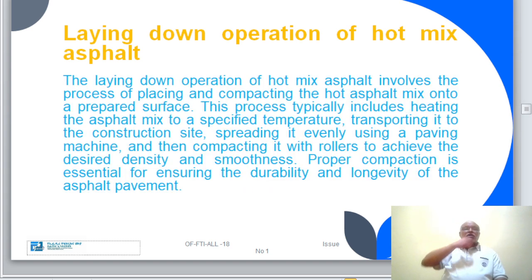The track paver, owing to its long and stable track, assures very good grip, stability, and maximum traction even under difficult conditions, and exerts less pressure on the underlying layers. They can pave wider mats compared to wheel pavers, which can be as wide as 14 or even 16 meters. Both asphalt pavers consist of two basic parts, the tractor unit and the screed.